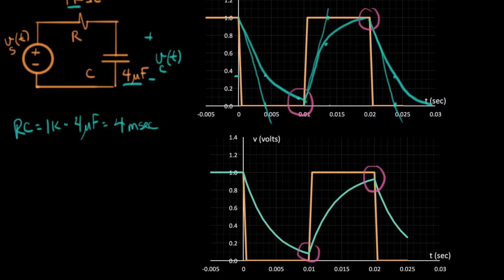So that kind of intuition, that kind of understanding of an exponential curve really makes you very quick. You can do this manually, and in your head, you can sketch out what these exponentials look like. The time point here, this line right here, that's RC seconds after it drops. That's the basic thing. And then the other one is this point right here. That's about 37% of where it started from. 37% to go.